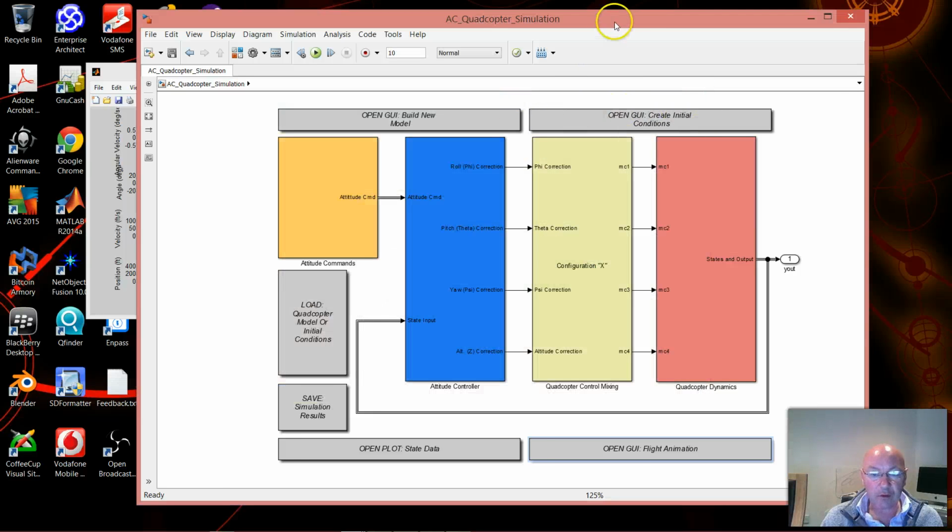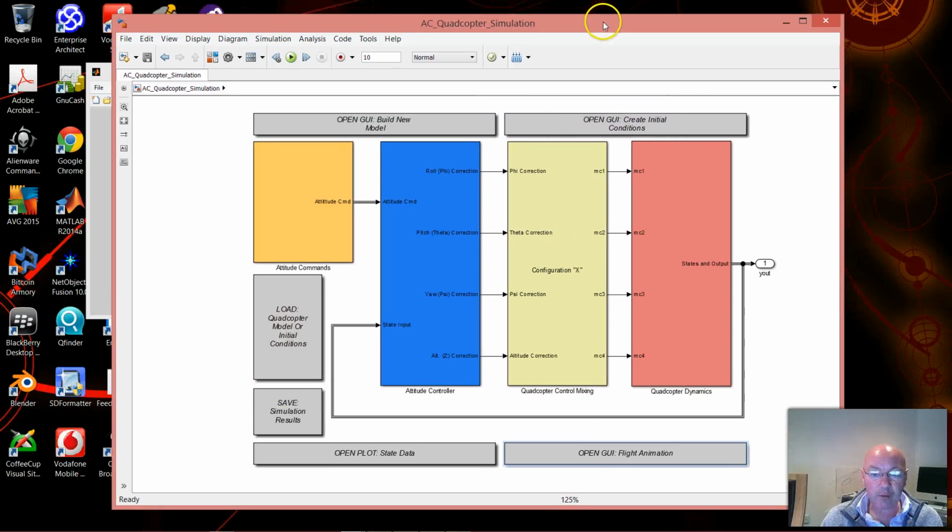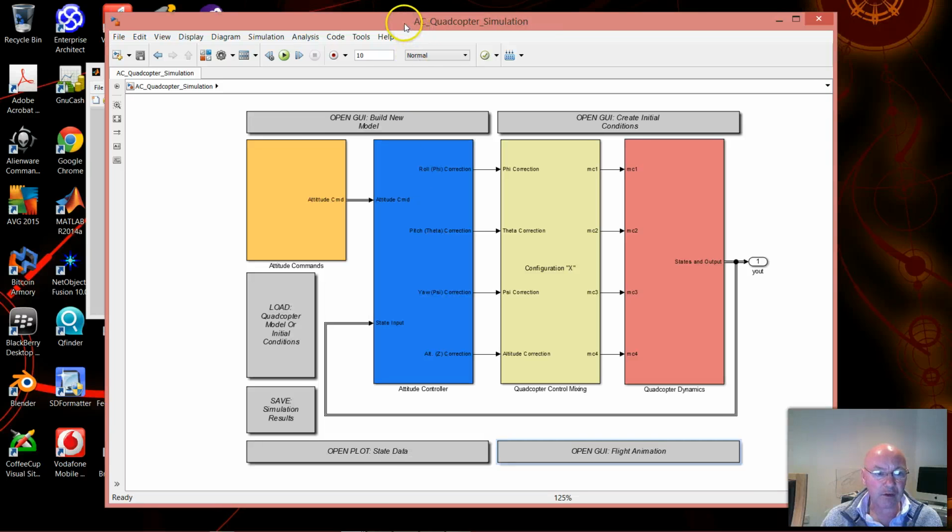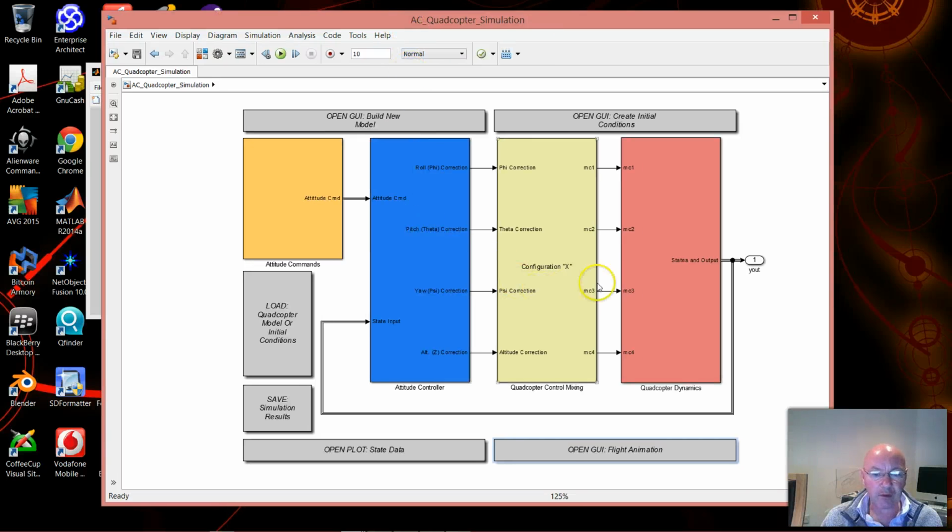Now, this particular model is not capable of generating code, as it has states in it which are not discrete. In other words, it's got states which require simulation at periods in between discrete intervals, and we are only capable of simulating discrete intervals when the model is put into hardware.